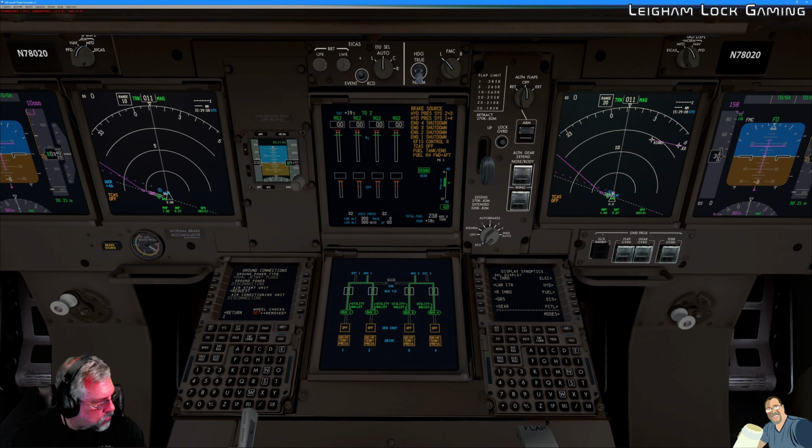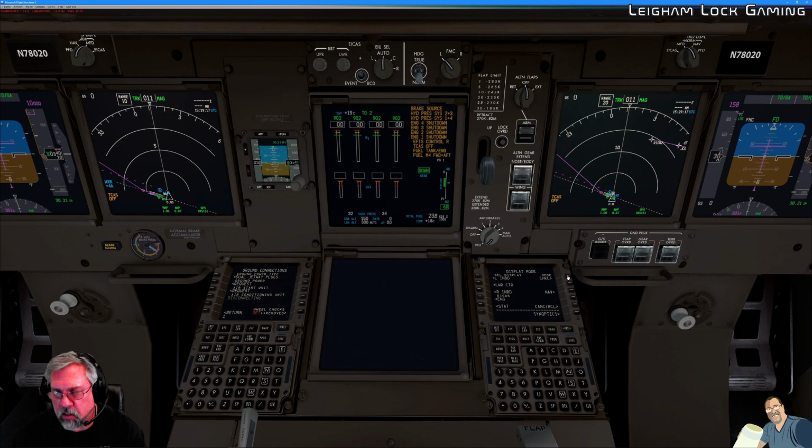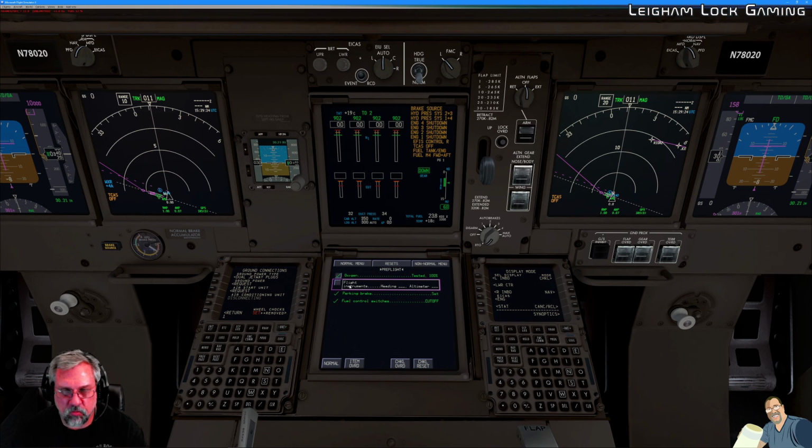And at this point, I have call pre-flight checklist in my checklist. So pre-flight checklist. Pre-flight checklist, oxygen tested, 100%, check. Flight instruments, heading 301 degrees. Altimeter 3021, set, check. Parking brake is set, check. Fuel control switches in cutoff position, check. Checklist is complete. We are good to go.